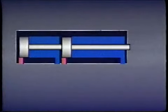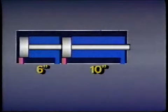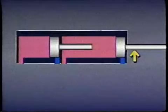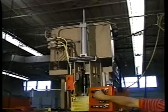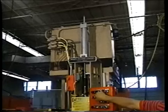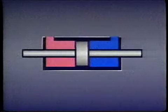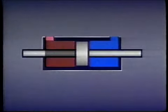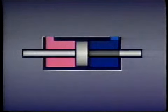For example, this duplex cylinder, with strokes of 6 inches and 10 inches, can move loads to one position when both pistons are at one end, to another position when the 6-inch stroke is extended, and to a third position when the 10-inch stroke is extended. In some applications, a cylinder must extend and retract its rod at the same velocity. When this is necessary, a double rod cylinder can be used. As long as the rods on both sides of a piston are the same diameter, the area on each side of the piston exposed to flow will also be equal, so rod velocity will be the same.